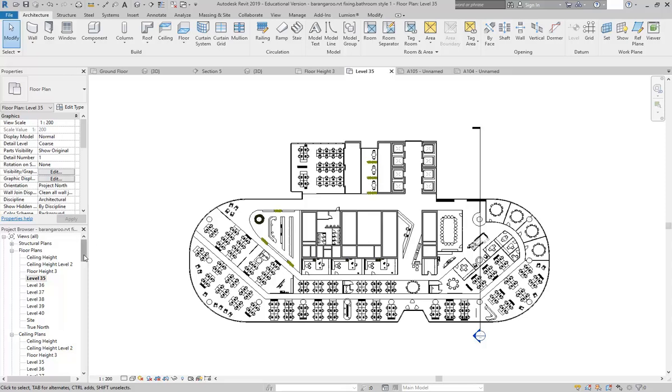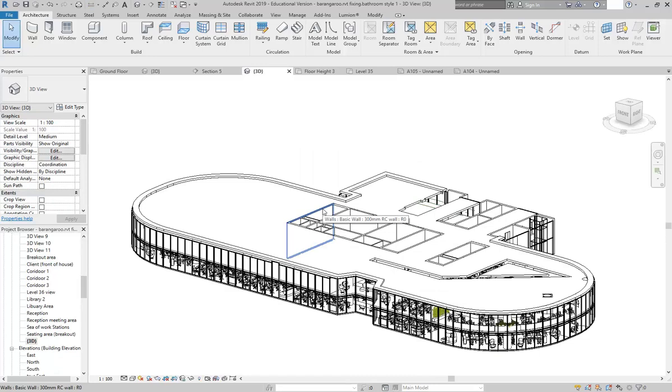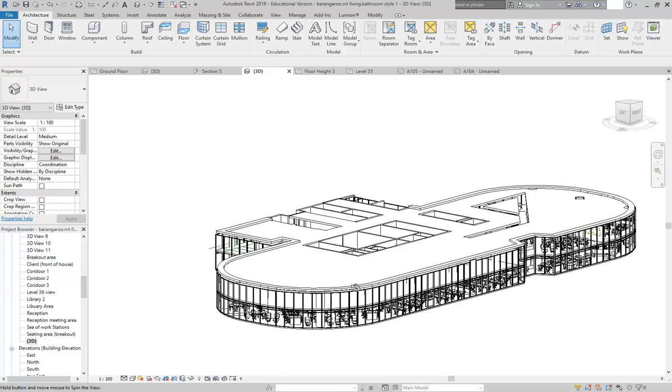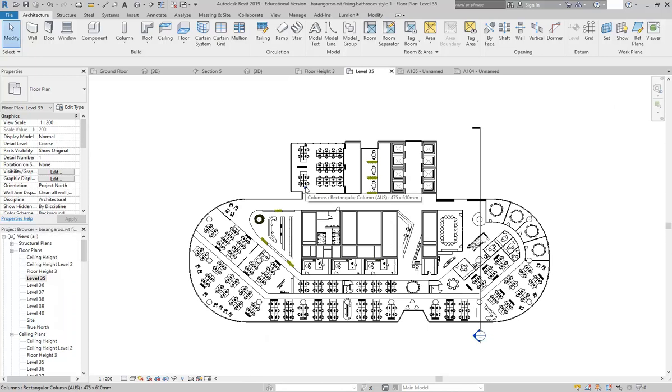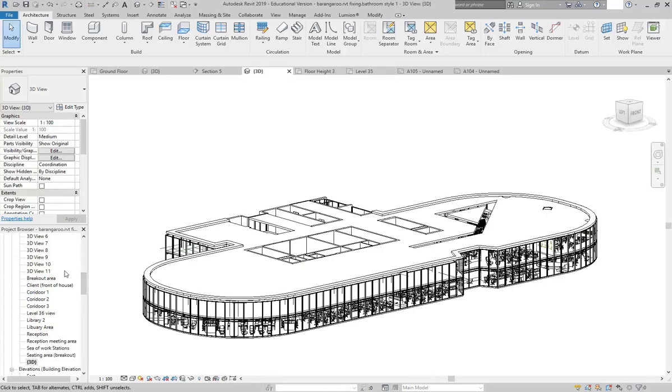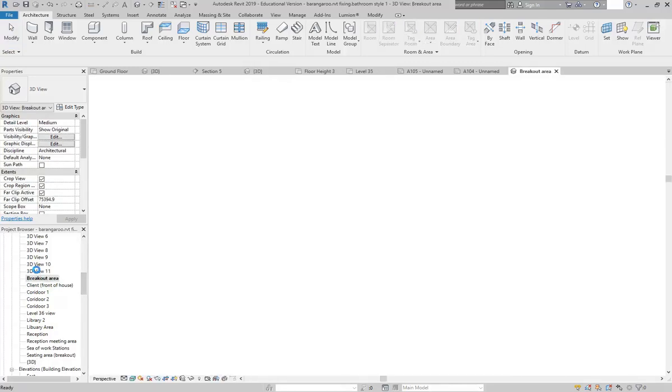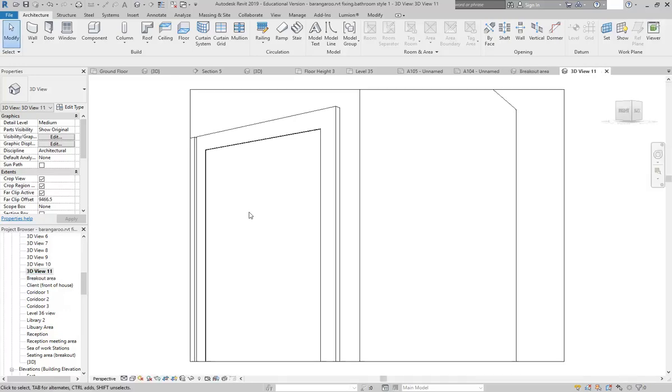The time you need to maybe think about that is if you ever want to export a 3D view. If you export from a view like this, what do you think you'll get back in AutoCAD? Is it going to be a drawing similar to what I'd get with a floor plan like this, or something different? Something different, yeah, that's right. If you export from a 3D view like this, or a perspective view, it gives you a 3D model back in AutoCAD.